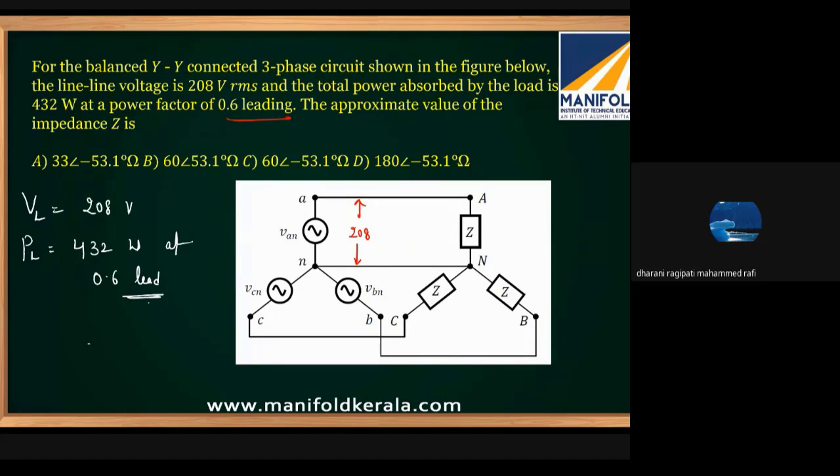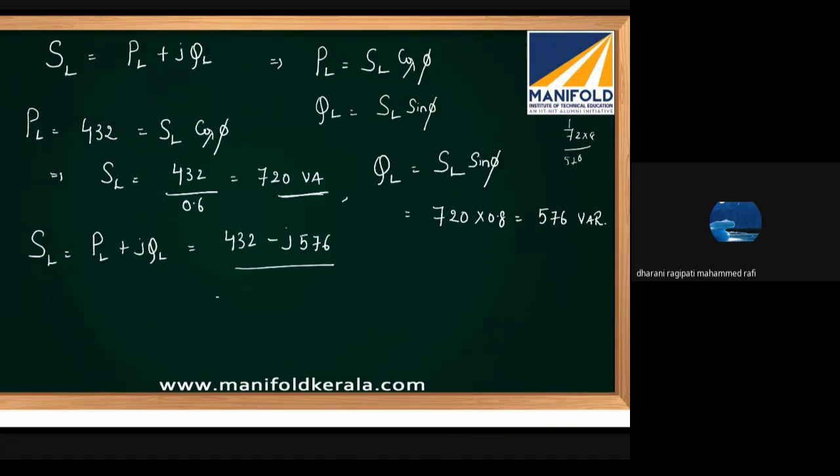Leading reactive power, whose polarity is negative. Be careful. So your QL is minus SL sin phi here because the power factor is lead.